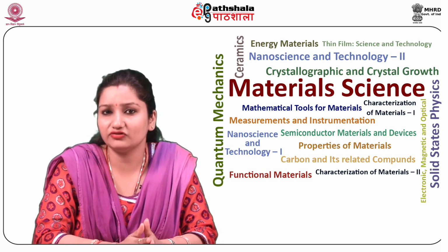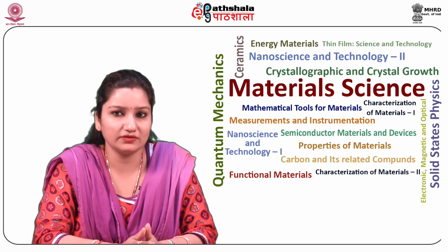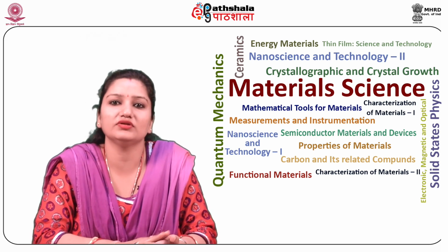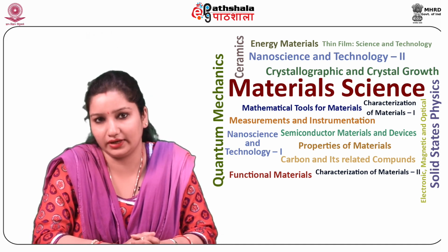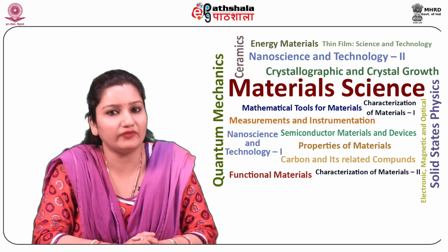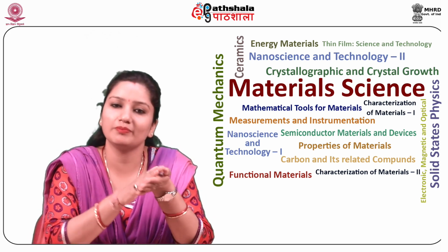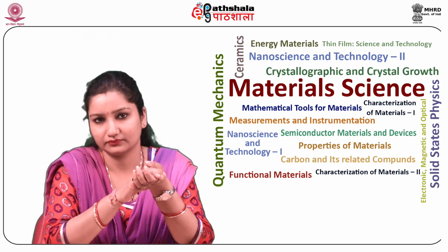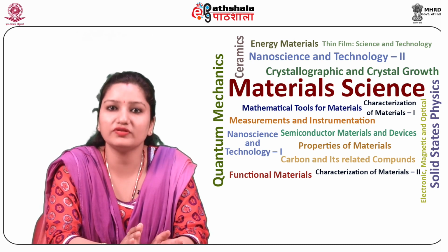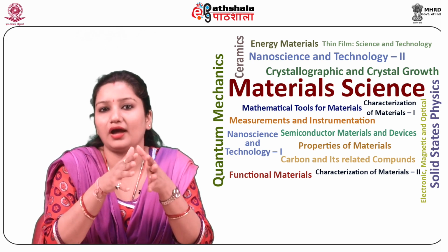Etching is an essential step during microfabrication. The process of etching involves both chemical and mechanical mechanisms leading to the removal of the material which is not protected by the photoresist. Etching can be done either in the form of wet etching or dry etching. Wet etch is perhaps one of the simplest forms of etching method. It requires an etchant solution such as an acid that removes the underlying film, reacting chemically, leaving the photoresist intact.